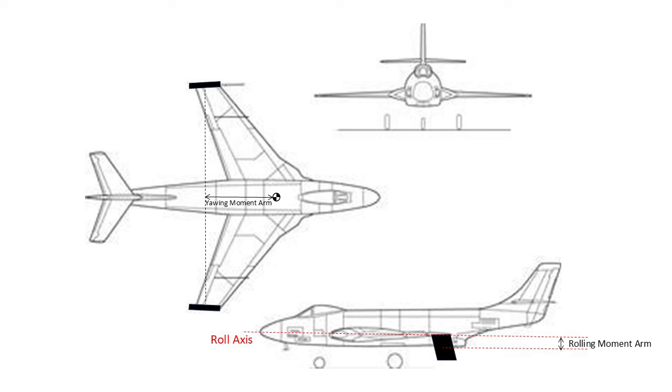Now, alternatively, consider a downturned winglet. As we learned a few minutes ago, the downturned winglet will generate a force pointing outwards, so when the aircraft rolls to the right, and the left wing generates more lift than the right, and the left winglet again inherits some of the wing's increased lift, this outwards pointing side force produced by the winglet increases. Since this is behind the CG, this will yaw the aircraft to the right and into the turn.